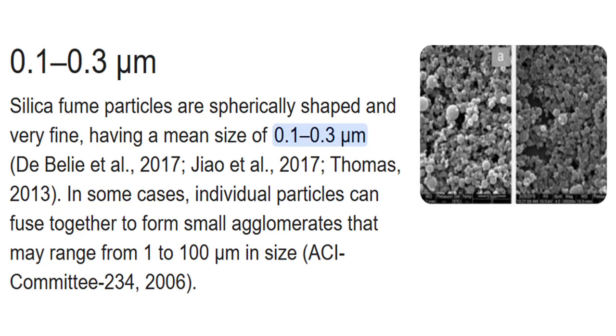The particle size of silica fume is incredibly small, typically below 0.5 micrometer, with an average particle size of only 0.1 to 0.2 micrometers. This makes it much smaller than other materials commonly used in construction, such as cements, fly ash, or mineral powders, with the particles being approximately 1/50 to 1/100 the size of cement.